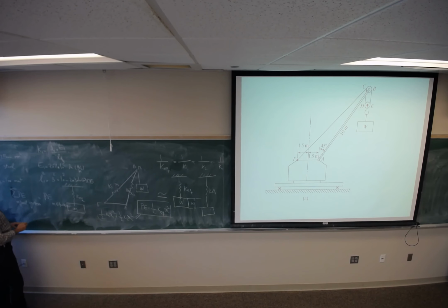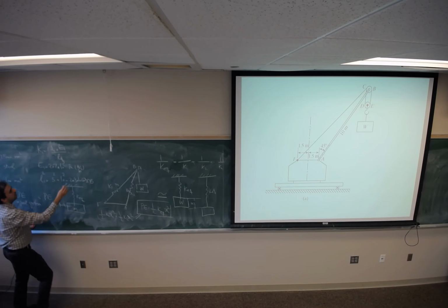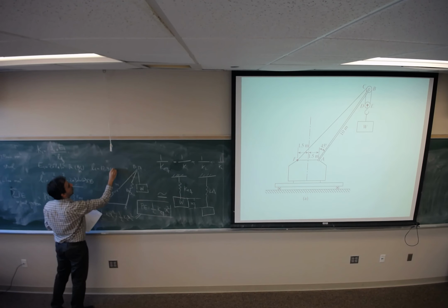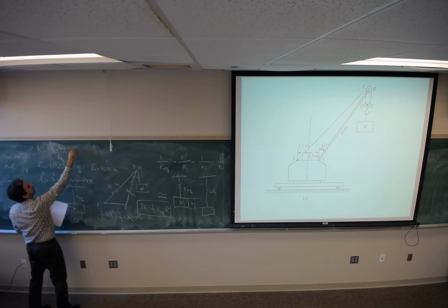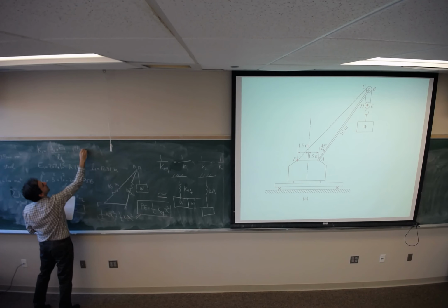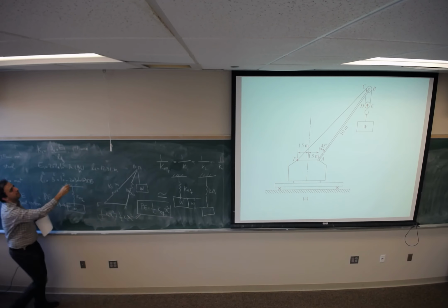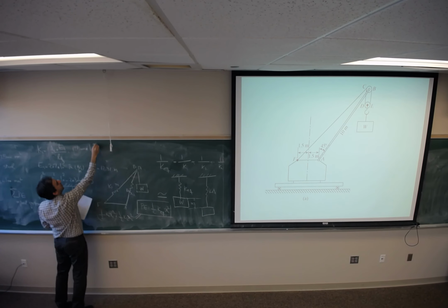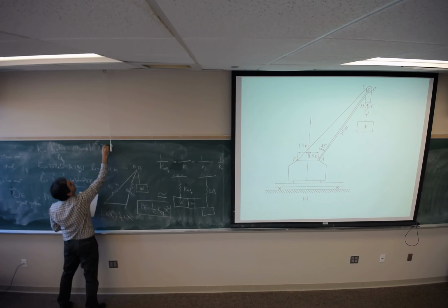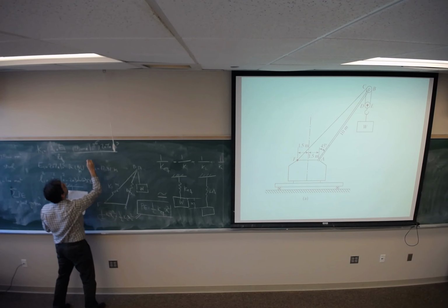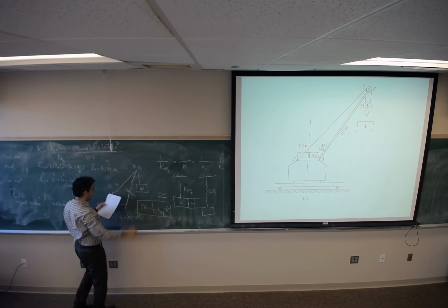Cosine rule, I can find L1. So L1 would be 12.31 meter. So if I plug in the 2,500, I should change millimeter square to meter square, 10 power negative 6, times 207 times 10 power 9 divided by 12.3.